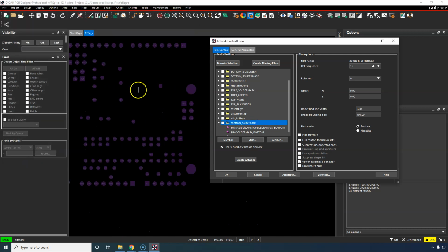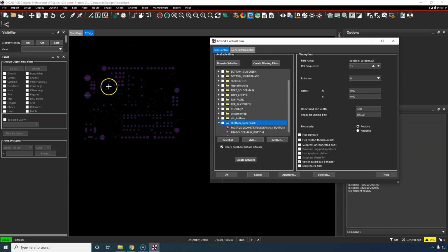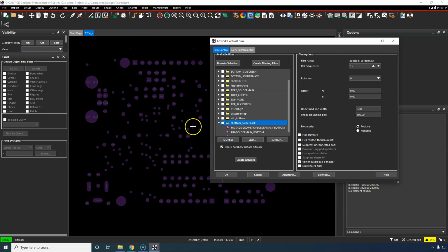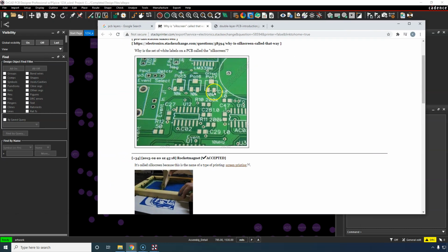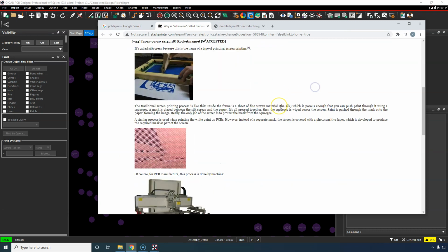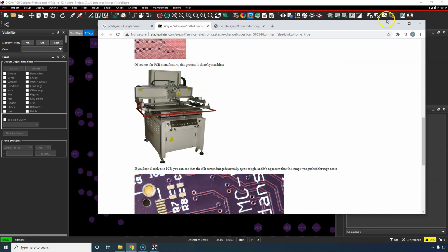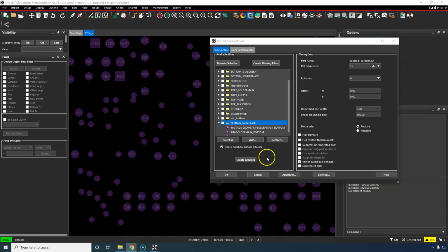Now, I wonder if that'll even show. Let's right click. Display for artwork check. Aha, there we go. See? All the vias exposed. See, they can't hide now. There's nowhere to run. All right, so move that out of the way.